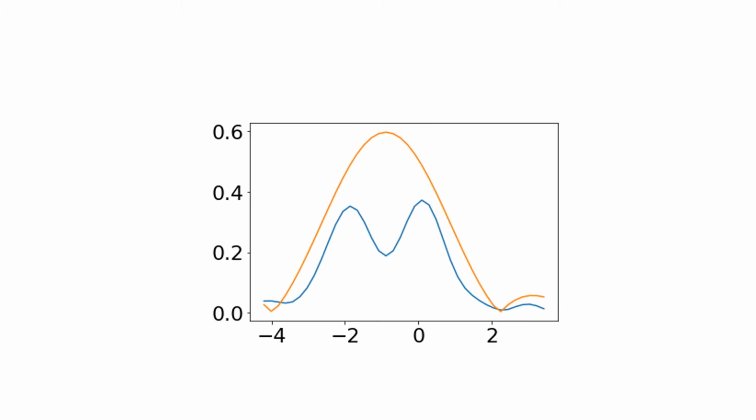So here are the plots that we see when we use the same least squares analysis in blue with the phase screen at the midpoint to resolve those two input signals, and we see that we have resolved the two signals with the phase screen, and then the yellow curve is what we had without the phase screen. So we have definitely increased the resolution of the system.